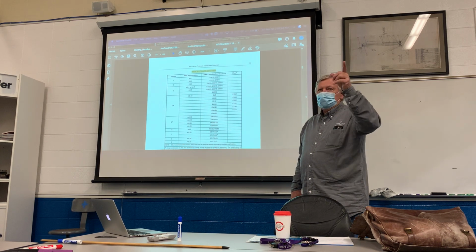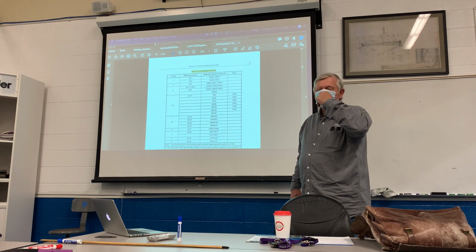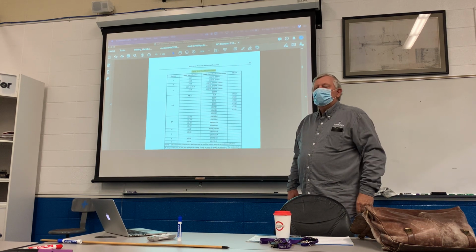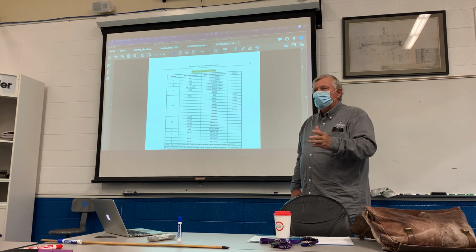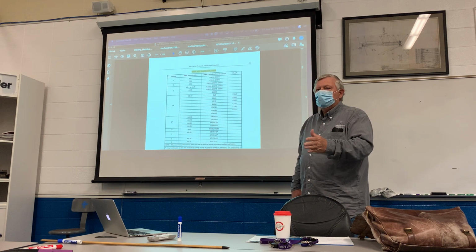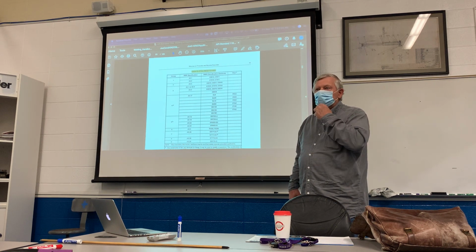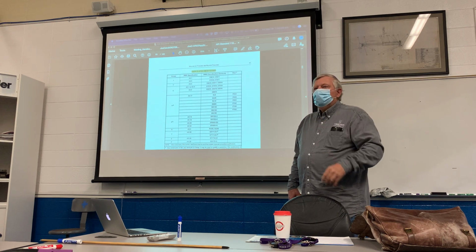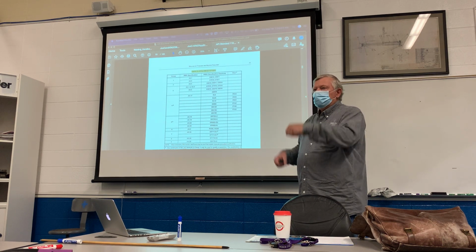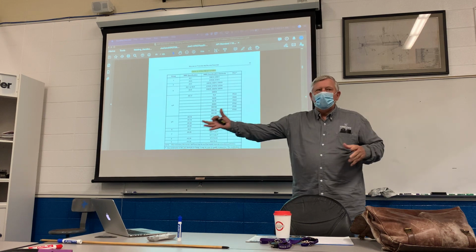Just a quick story. I did a pipeline north of Evanston, 16-inch pipeline, and I told him it's a 300 degree, 275 degree minimum preheat. This was hard pipe, it was X70. So, I had them set up, a couple guys with rosebuds right in front.